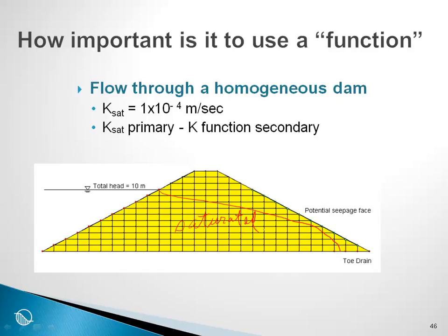And the position of the zero pressure contour is relatively insensitive to your function. And once again, the pressure distribution is quite insensitive to the function that you have defined. Now, the height of the capillary zone, as we have demonstrated here, is related to your conductivity function, and at what point does air begin to enter the soil, or the point on the function where we have the air entry value.